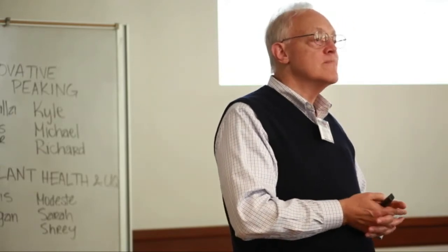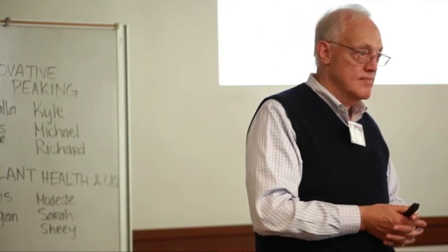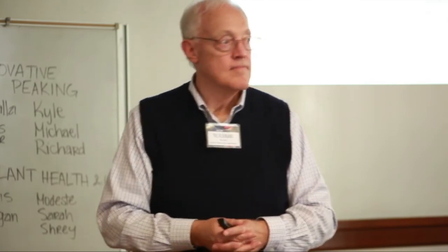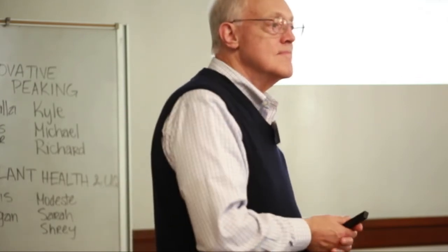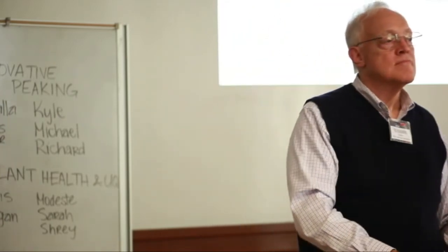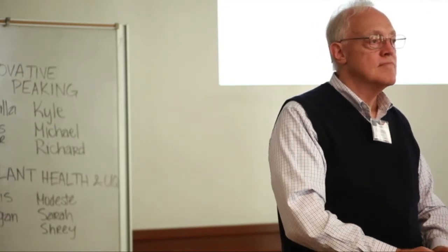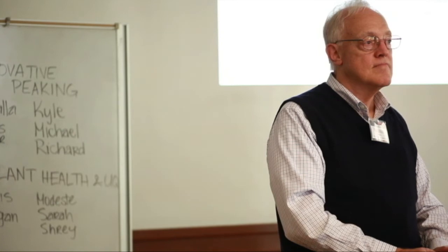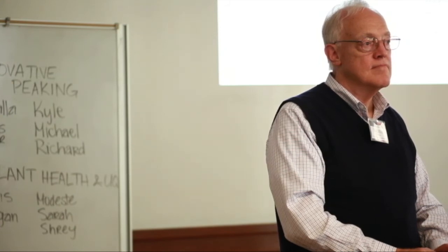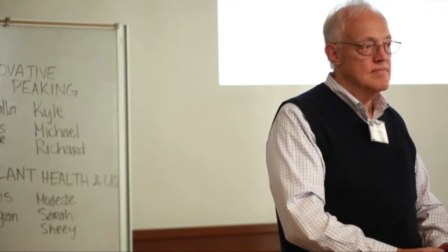Well, so I'd say, speaking about Amir's program with Southern, when you look at what PRA is at level 1, 2, and 3, it ultimately comes down to radioactive release to the public. That's level 3. You say, what is your initiating event that can lead to that? And if you design around preventing this level 3, the right side, which is actually affecting the public, and look at what you're actually most likely to have a release from, it can determine how important your initiating events are. And so you can use that same approach for any reactor design.